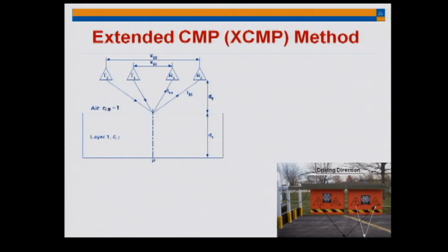I'm going to emphasize here why we are doing this. If I measure the dielectric constant just from the surface, that will be okay if it's a new pavement. If it's an old pavement, then that will not give me good results and will give me significant error, because it will be just the surface dielectric constant.